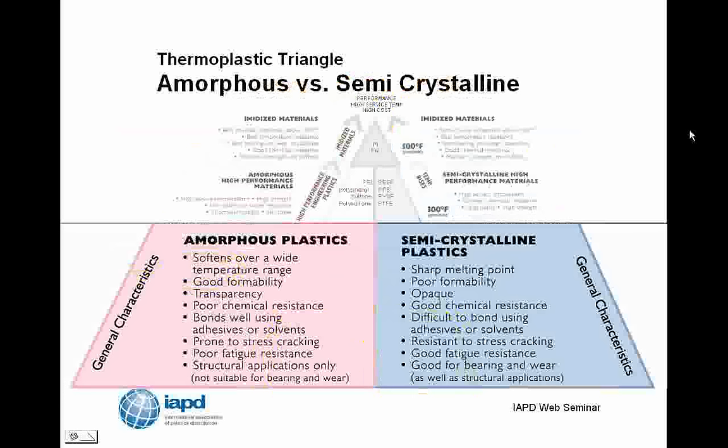As one very eloquent thermoformer told me, they got no hot guts. They don't have that nice rubbery phase over a broad temperature range. It's over a much narrower temperature range. I'm not saying you can't thermoform semi-crystalline plastics. You certainly can. People thermoform polyethylene truck bed liners every day. What I am saying is it's more difficult than thermoforming amorphous plastics. You need to have special molds, and you have a much narrower processing window.